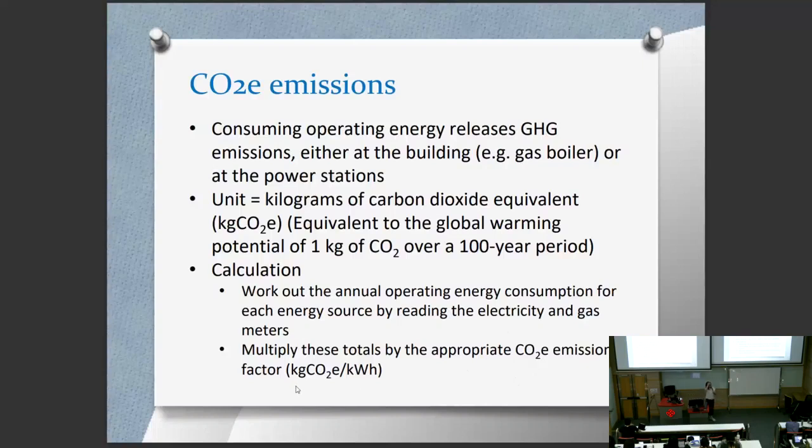For example, if I want to calculate the operating carbon of my home, then I will collect the electricity bills for the whole year. I live in the New Territories, so the provider of electricity will be CLP, and I can go to the website of CLP to check its emission factor.